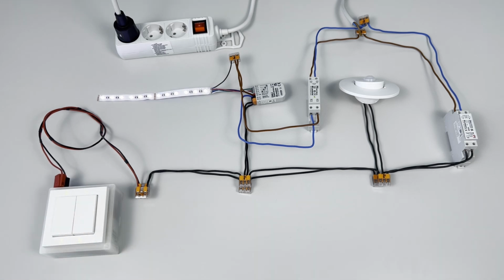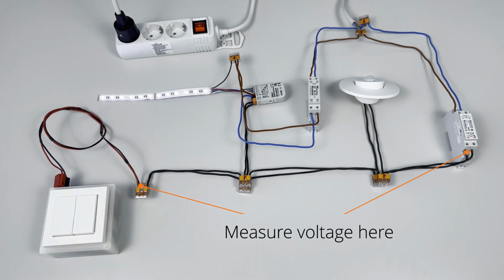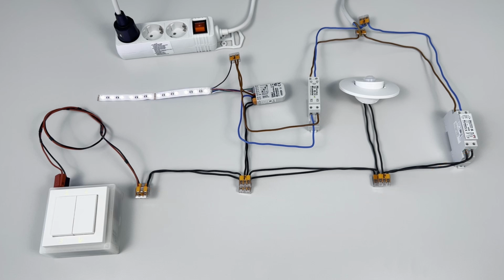To verify this, measure the voltage of the DALI power supply and the furthest device from the power supply using a voltmeter. The voltage drop between both measurements should not exceed 2 volts. The DALI voltage should be at least 11.5 volts at the power supply and no less than 9.5 volts at the furthest device. Note, for accurate readings, ensure that there is no communication occurring on the DALI bus during measurement.